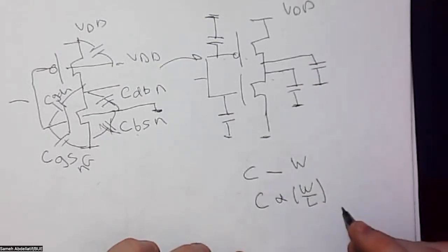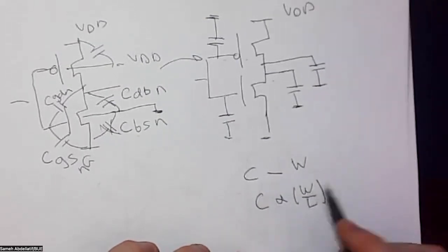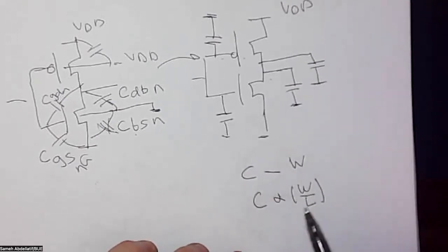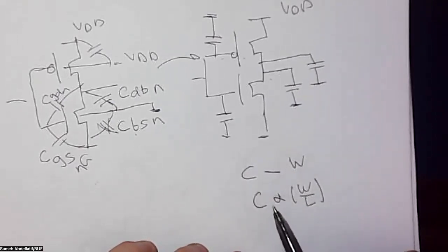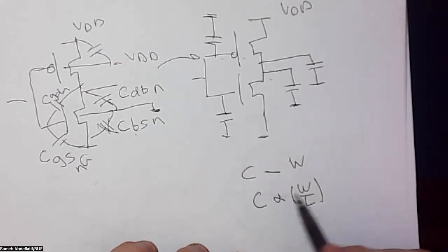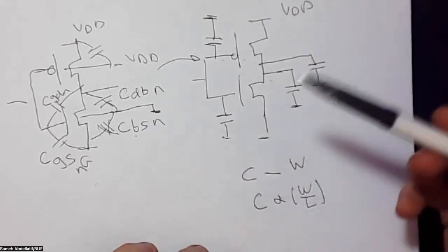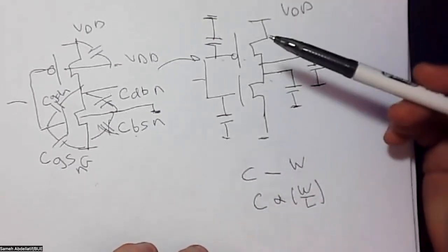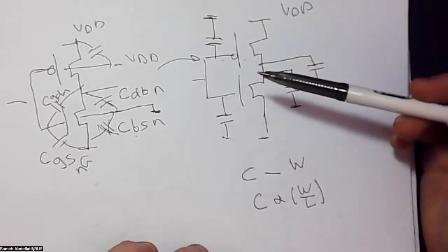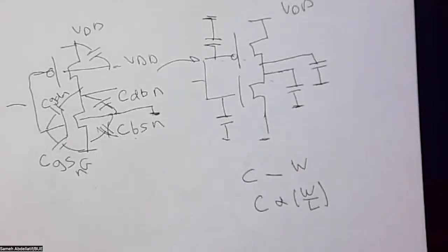when we consider different analog or digital design aspects. Why am I considering this point? This is simply because when W over L changes, capacitance will change. And as all of you have already studied, I think, the concept of PMOS sizing, which is related to the variation between the electron and hole mobility.